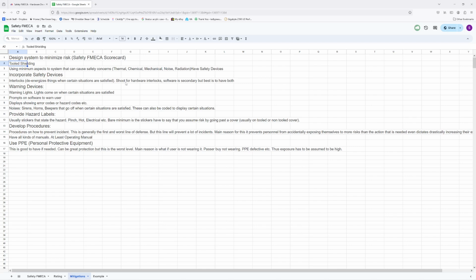Generally in that case, your hardware interlocks are usually at an extreme case scenario. So if you have a thermal runaway, it's at maybe the very end of what your heater can go to, right before you have damage. Now, it would be great if you had software interlocks that would catch the problem before it hits the hardware interlock and maybe some damage to the equipment happens, but you save the personnel, right? Save the machine if you can, right?